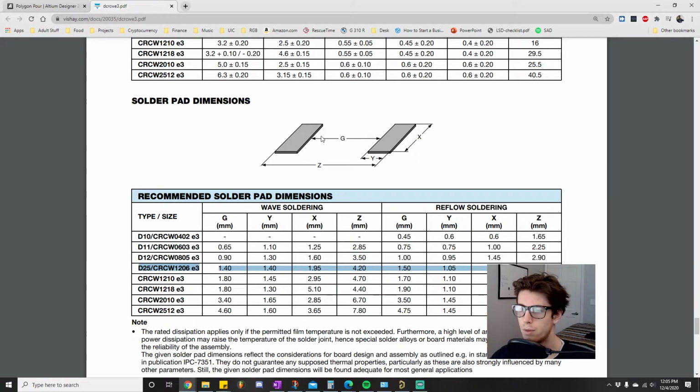Well, we know from edge to center of this pad is G plus 1/2 Y, right? Hopefully that makes sense. Whenever we want to go halfway, that is going to be the center of this pad, so 1/2 Y. Then we know from this edge to the center of this pad is another G plus 1/2 Y. So only count G once, of course. I hope that makes sense. But then you should figure out that the center to center is G plus Y.